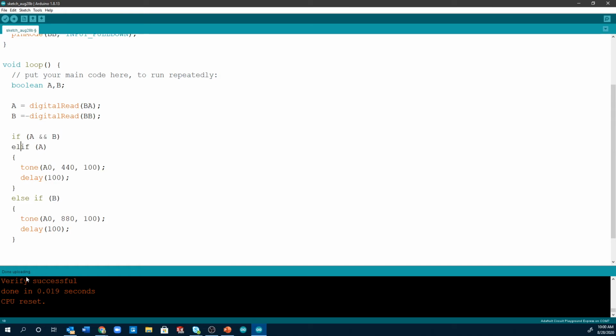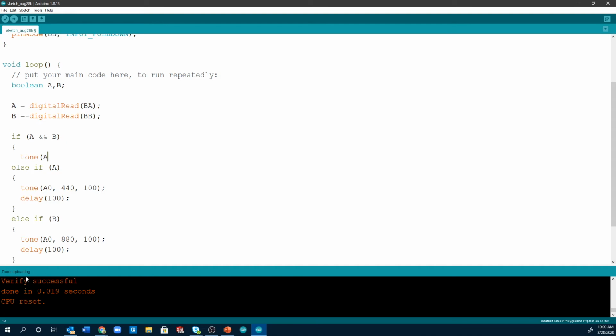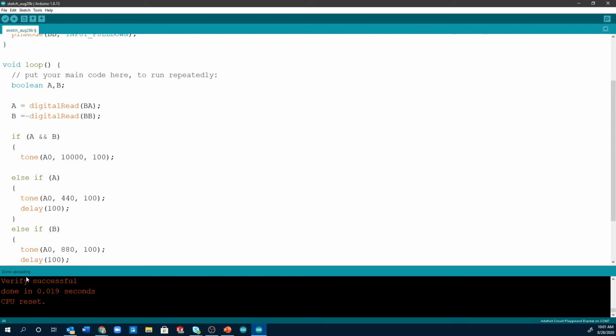We're going to change our A to an else if. And we're going to say if A and B, let's go ahead and do a tone. A0, and let's do something like 10 kilohertz. I'm going to play that for 100. And let's make the delay here 150.